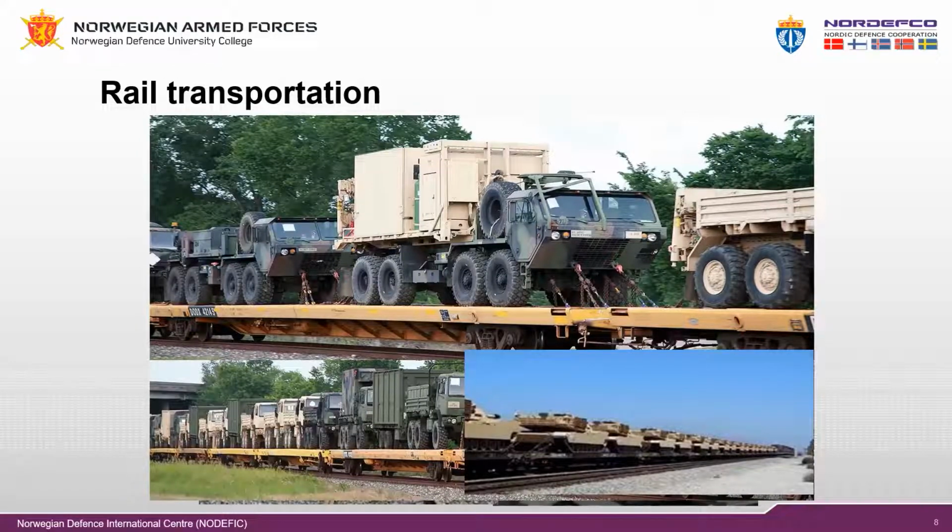In the case of rail transportation, capacity is measured between two selected points, such as a base area and a railhead. Provided there are no other limiting factors, it is a product of the payload of the heaviest train and the number of trains per day that can be worked in both directions over the limiting sections.